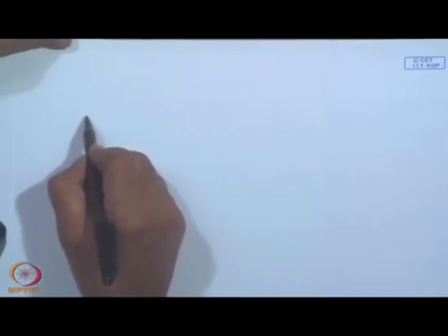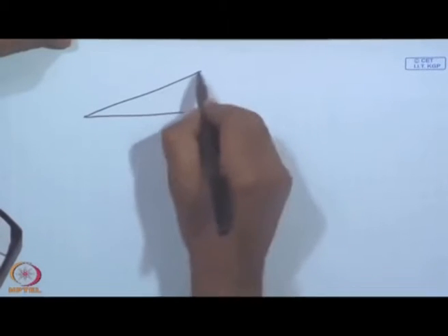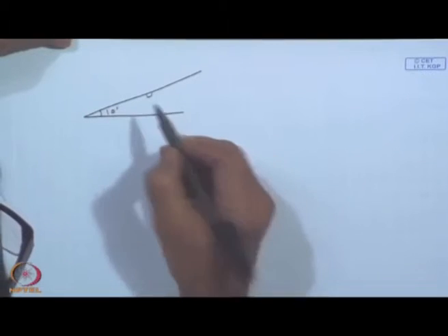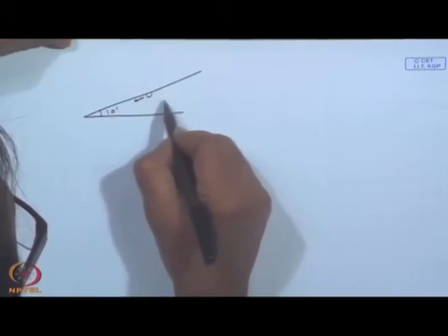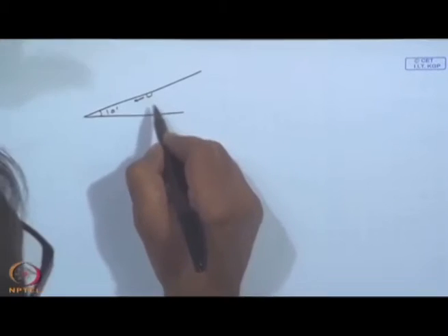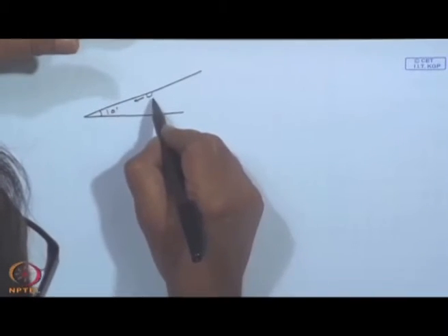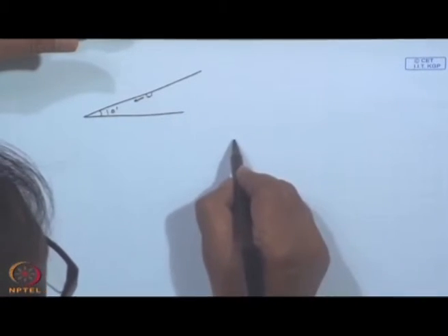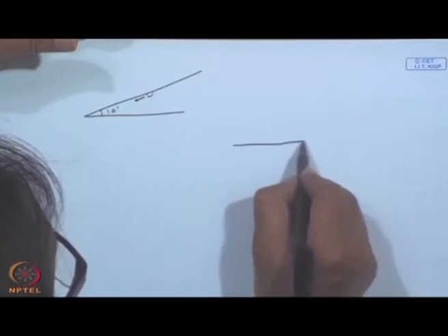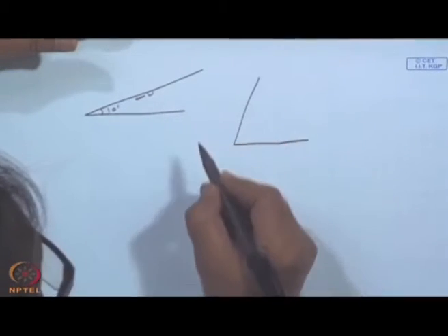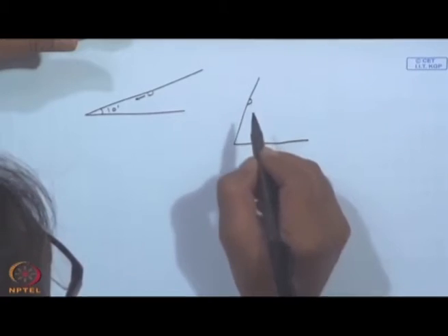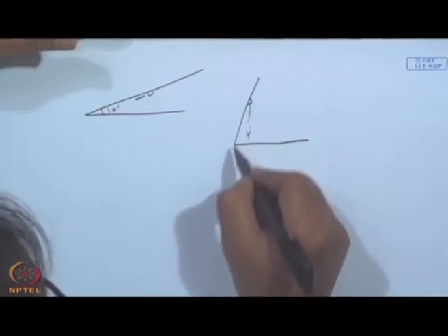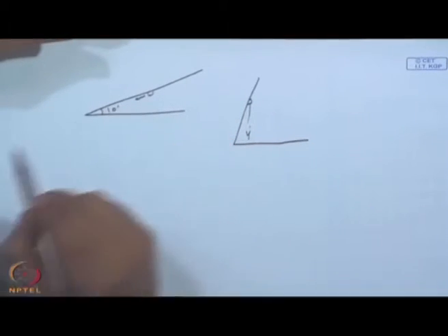And then this angle, if you find a drop, it tries to come this side because of gravity, some component in the vertical direction, and it tries to stick to this because of surface tension. And if the angle is too large, it may come down straight and not flow along the surface.